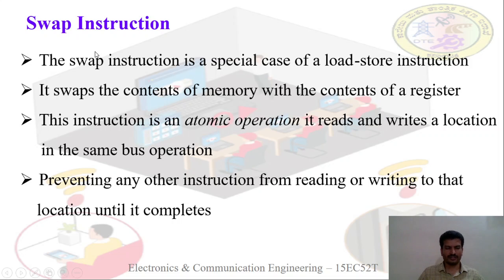So next is the swap instruction. So what is swap? A swap instruction is a special case of a load store instruction. It swaps the content of memory with the content of a register. So in 8051 microcontroller, you have studied swap instruction also. There you have studied SWAP A.